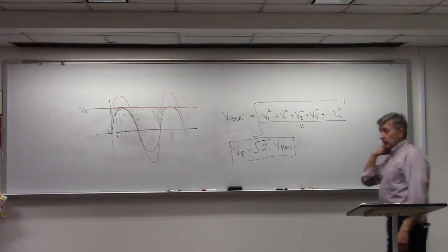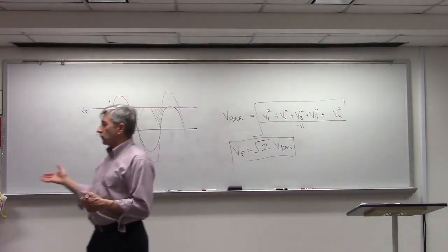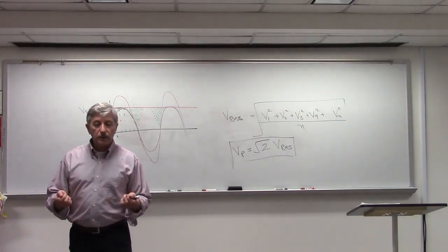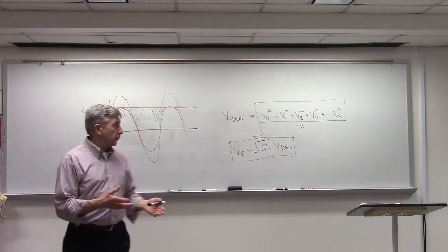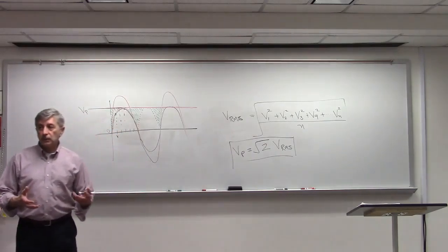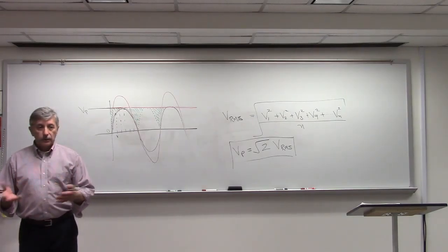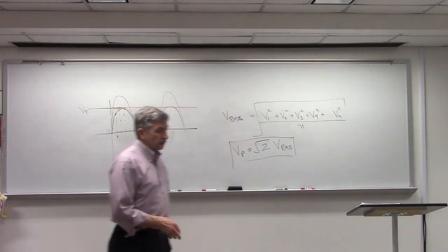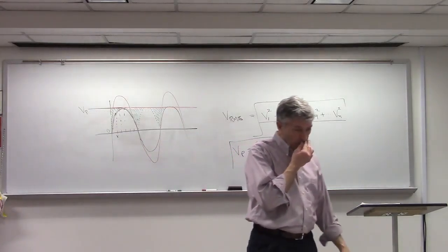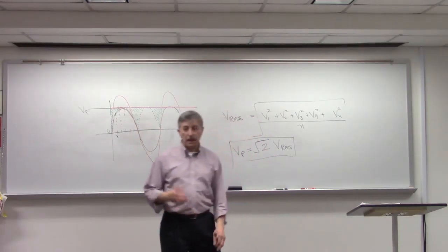So that comes to 169.7 volts. If you were to put an oscilloscope, stick the probe into a receptacle and actually look at the waveform, the peak value for a standard receptacle is going to be about 170 volts. Even though your meters will show 120, 115, 110, it just depends on where you are. Okay? That's the formula, and that's exact.